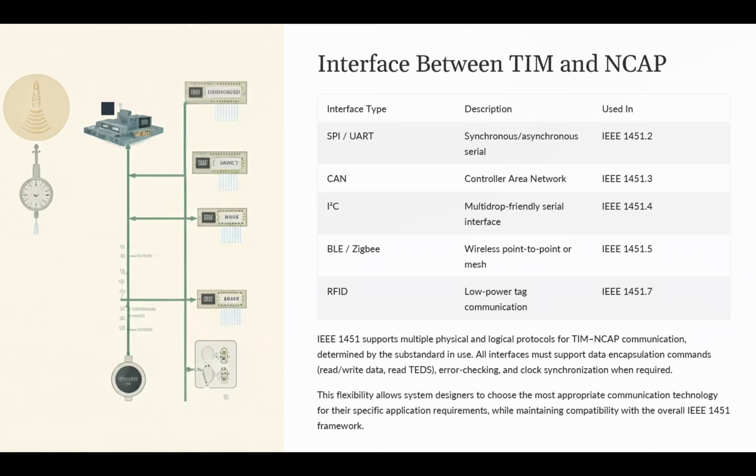It also, when we talk about time critical applications, okay, so time sensitive applications, that interface should support clock synchronization between the TIM and NCAP. So we make sure that the time stamped measurements are accurate and consistent throughout our network.